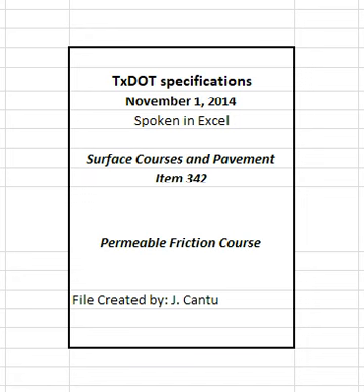4.4.2.1.4 Submitting JMF1. Furnish a mix design report, JMF1, including Hamburg and overlay results. Provide representative samples of all component materials and request approval to produce the trial batch.